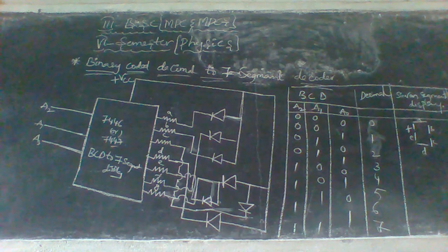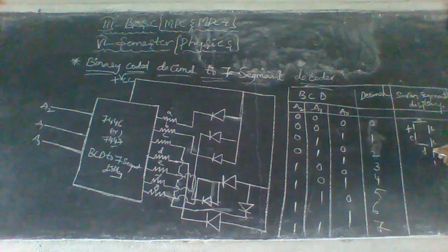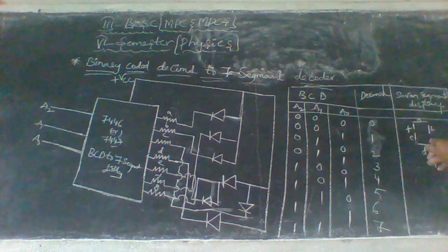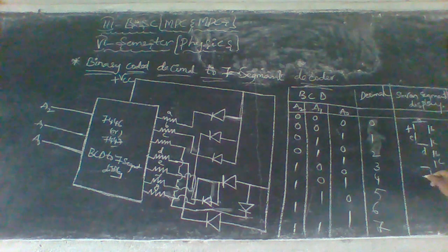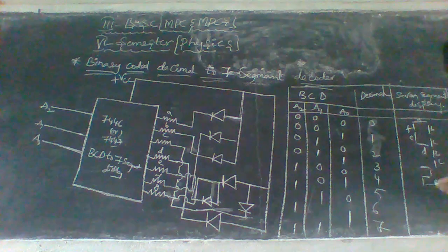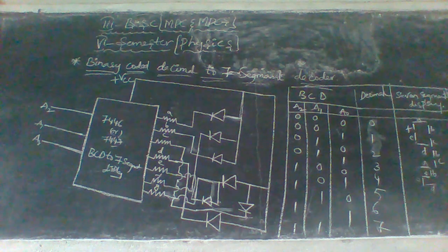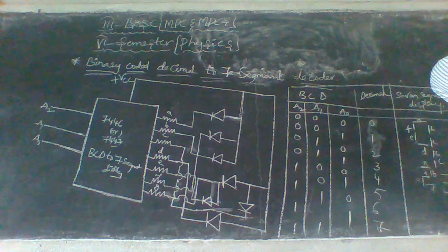and 1 will be displayed on only B, C. Okay, and 2 will be displayed on A, B, G, E and D. And 3 will be displayed on A, B, G, C and D.